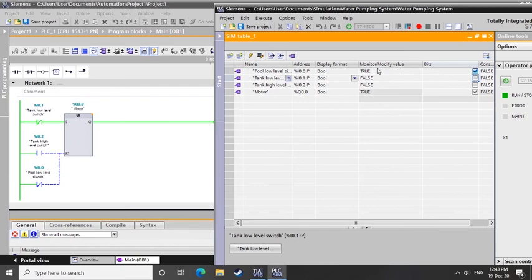So until the pool does not have any water, the sensor will detect it as inactive. And in this case, it will stop the pump, because as you can see here, the green has a direct input to the reset. So the pool level switch will turn off when there is no water inside the pool.